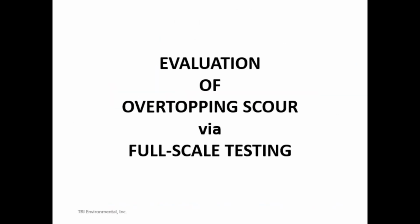Other high-energy applications include the use of HP-TRMs for protection against spillway flows and levee overtopping. Once again, not only is special anchorage required, but a special assessment of the TRM's ability to resist the unique scour forces encountered must be done. Unique large-scale tests have been developed to make these evaluations.